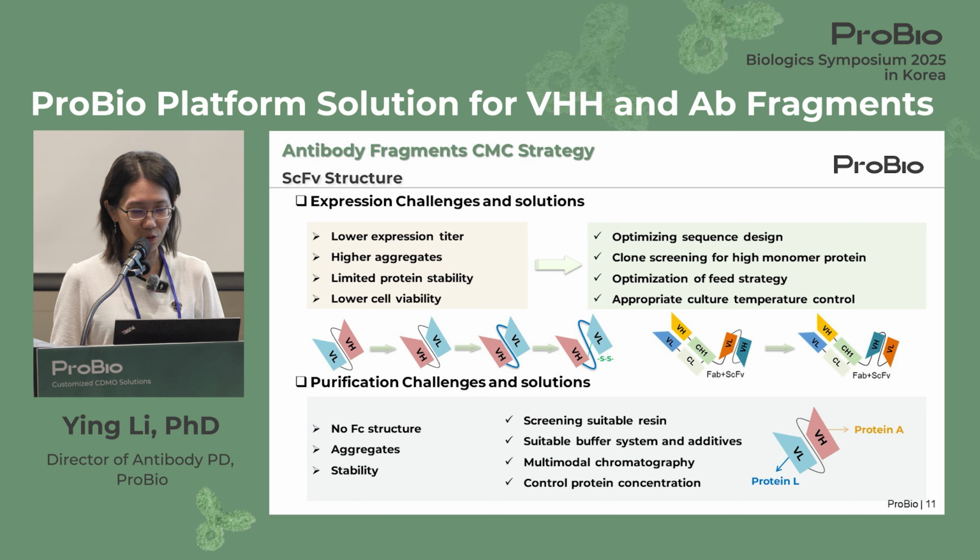So the solutions include screening a suitable capture resin, along with a buffer system and elution condition and additives, utilizing multimodal or mixed mode chromatography to remove aggregates and other aggregate species, and control the protein concentration to avoid degraded DS quality.